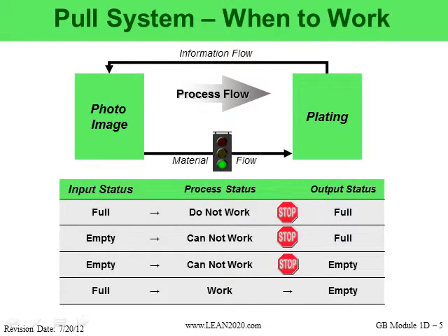One last comment that I wanted to make before we left the last slide is about the example I was talking about. If we had a large amount of product sitting in front of the plating department, some of that product may be sitting for weeks and weeks of time with film on the product. And this actually created some problems in the plating area where we had some film that started to lift off the panels, and in other cases we had film that, because it had stayed on panels too long, when we went to remove it later on in the plating process during one of the stripping operations, we actually had problems removing the film.